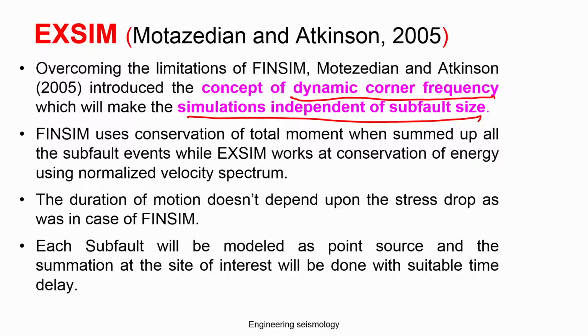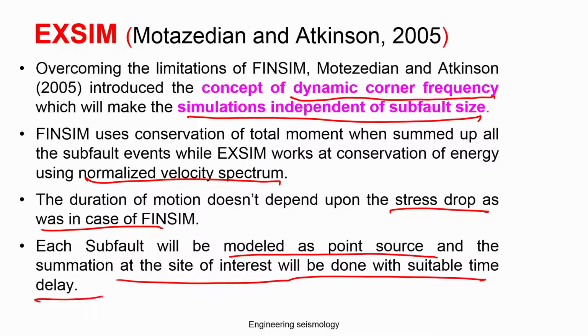FINSIM uses conservation of the total moment when summing up all the subfault events, whereas EXSIM works on conservation of energy using the normalized velocity spectrum. The duration of the model does not depend upon the stress drop, which is another benefit. Each subfault is modeled as a point source, and then the summation of the subfault events is done with suitable time delay. You can see that the point source model was the origin, where this mathematics and simulation concept has been expanded and studied in detail.